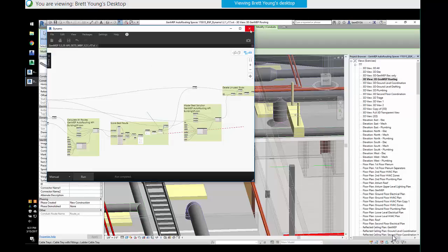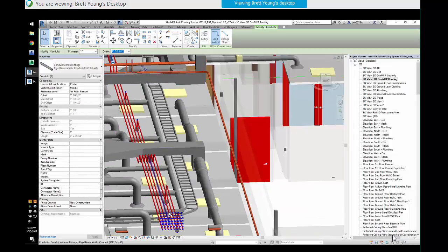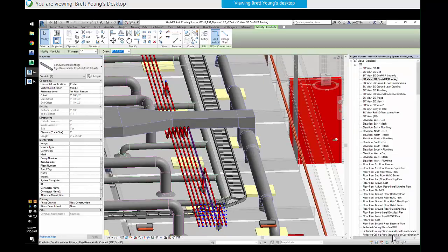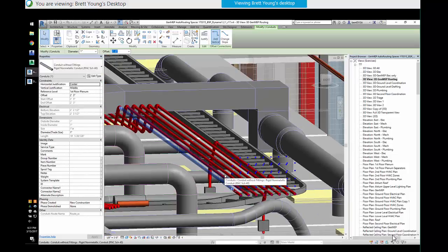Okay. You said that you have a start point and an end point, right? Yep. So why do you need to have those offsets at the start point? Let's see. Specifically in this example, they're going straight out of the start and working their way at that horizontal plane at 2'3" in the plenum, which I think is around 10 feet. So they're straight from the beginning, but then they hit that duct obstruction, so they have to go up or down. Oh, I see what you mean. I thought you were talking about at the start, you either are at one point or another point. But we go straight out from those start points, and we just run into something at some point. So I'd like to get over that duct, in theory, right?